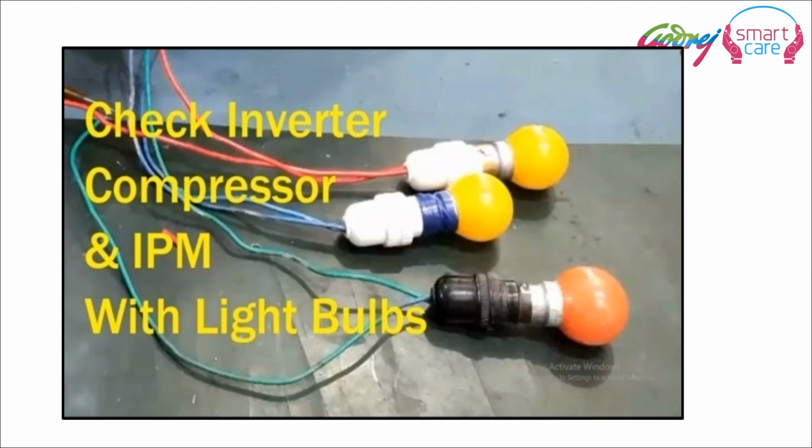We can check the inverter compressor and IPM with a light bulb. There's a small video which will help us to learn about how to connect the bulb with the respective PCB and compressor.